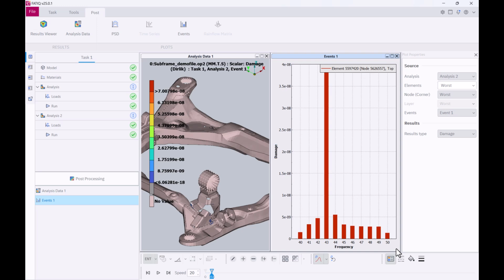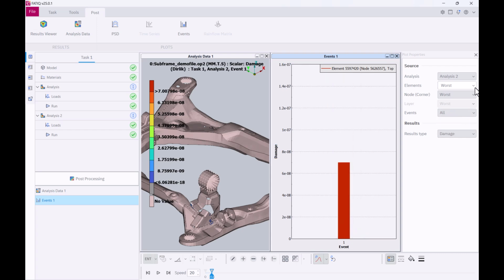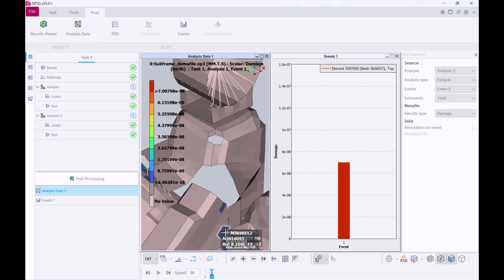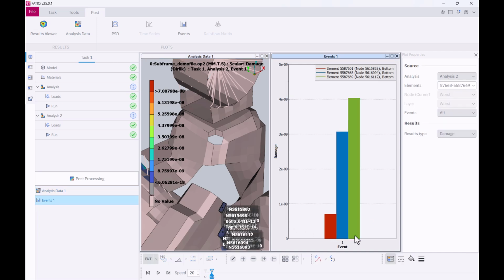10 sine wave sub-events are shown, as determined by the number of sine bands when the sine sweep was defined. All 2D plots have a direct interaction with the model. So, by modifying the parameters, the plots are updated. For example, more than one element can be chosen by the user with the option Pick. Directly the desired results are displayed on the selected plot.